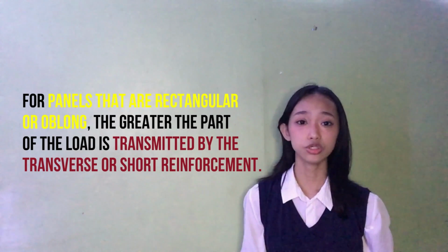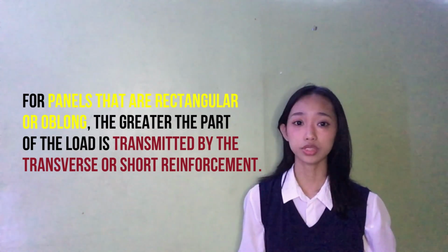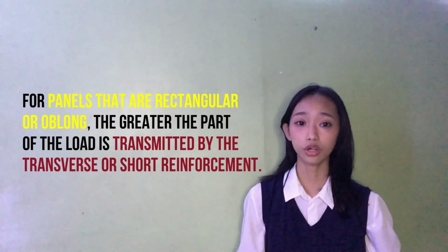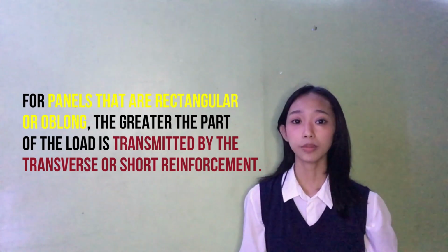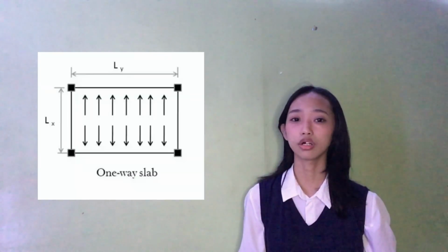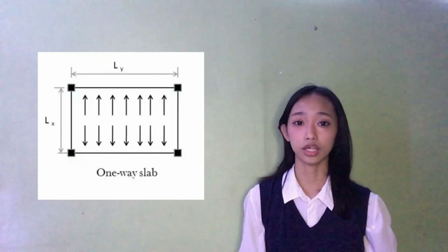The entire load is usually assumed to be carried by the short reinforcement and the long reinforcement used for shrinkage and temperature reinforcement only. Hence, the slab would become a one-way slab.